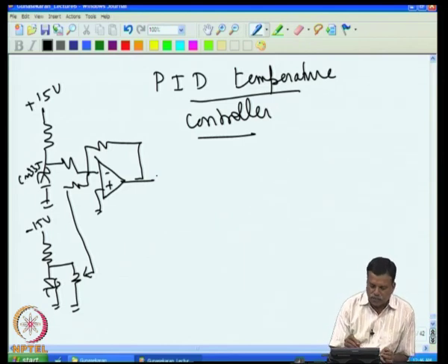So, that is the error voltage, and in the earlier case when the temperature goes up, this plus is going up, and then this will be going minus. So, to remove that we inverted this. So, that also can be done. Now, you got an error voltage here. So, when temperature goes up, this also will be going up.